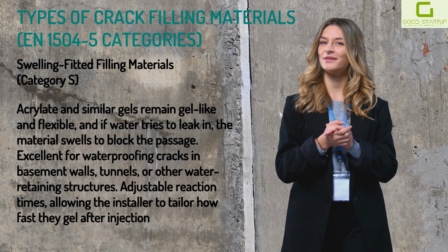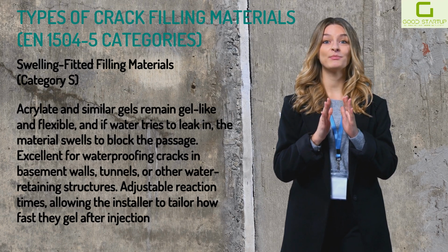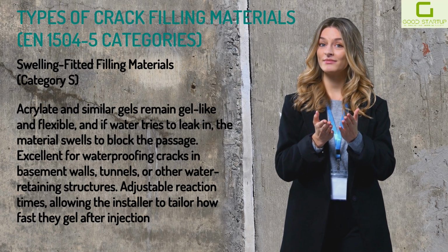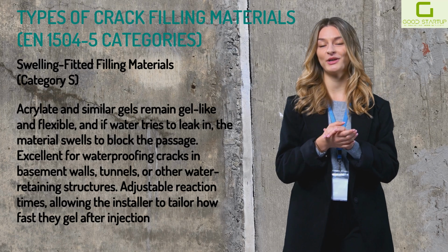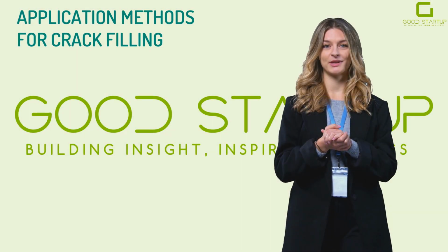In summary, swelling injection materials are chosen when stopping water ingress is the main objective. They often work in tandem with flexible resins. For example, a hydrophilic polyurethane that foams and swells can both seal a leak and remain slightly flexible. Proper application is as important as material selection.